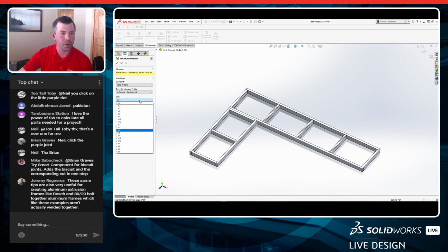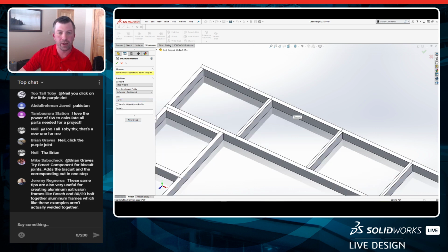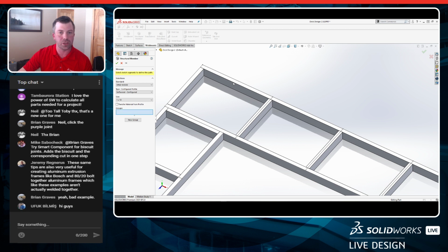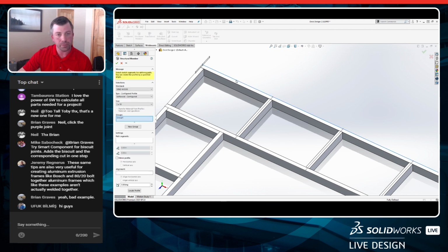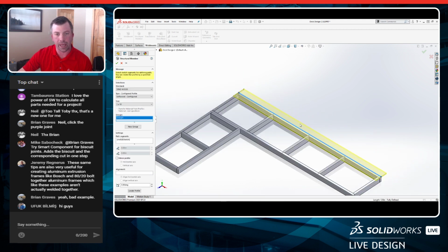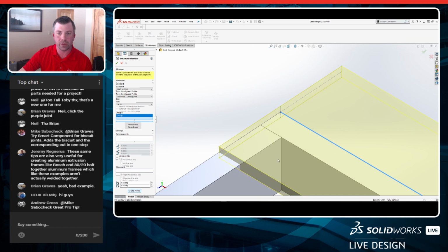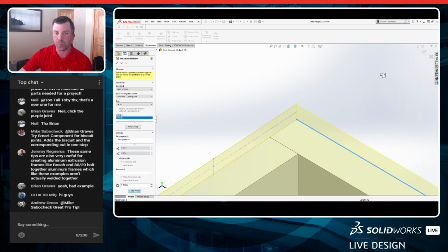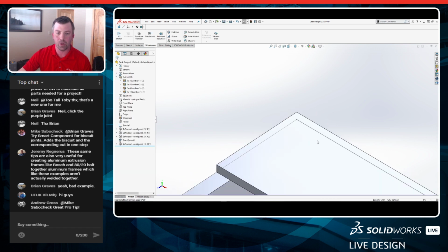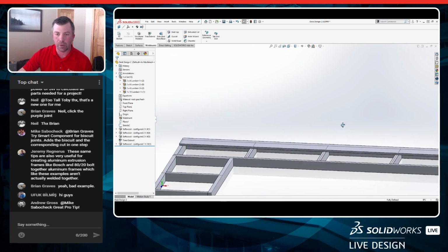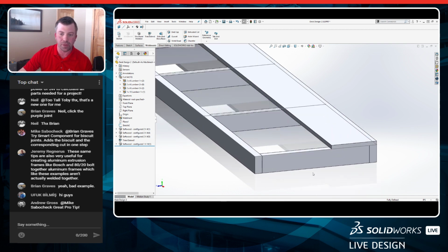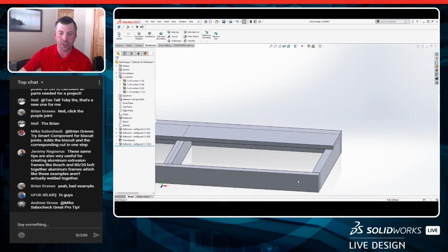So what I'll do is just come through here and we're going to change that over to a 1x10 profile in that softwood configured. And then using the same sketch, let's just generate out a single piece. That's going to lay that all the way down to the end. We'll find that profile and make sure that's flush against the wall and flush against the top. And there's my full extension. Now what I wanted to do though is extend this out a little bit further on the edge and the front.